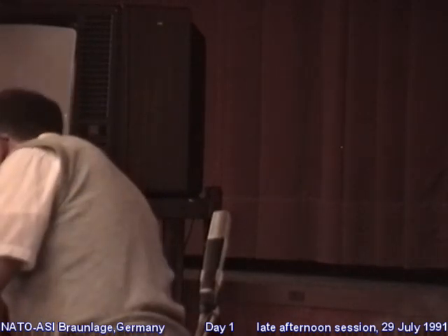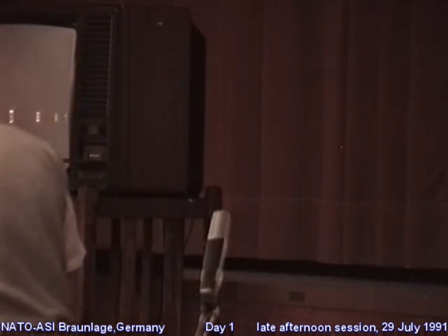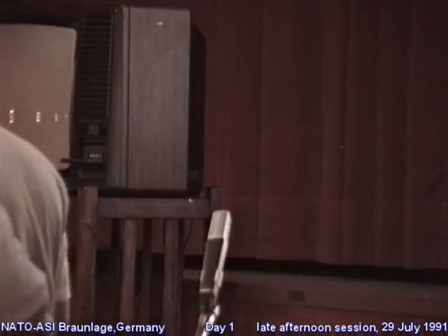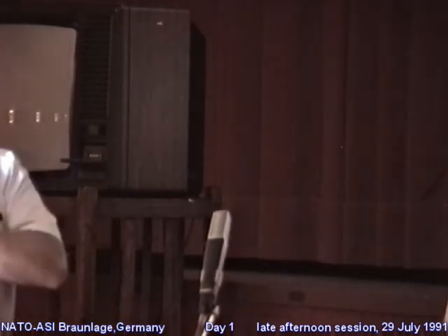You've talked a great deal about Mr. Cameron, so I'll share a little story with you. You used a Cameron Plint machine, and many years ago, maybe 20 years ago, he chose to do this classic experiment. He took a piece of steel, submerged the contact in mineral oil, and put some stearic acid in it. He varied the temperature, something that Tabor did in 1940 or '45. He changed the temperature and measured the friction coefficient, and then he found scuffing.